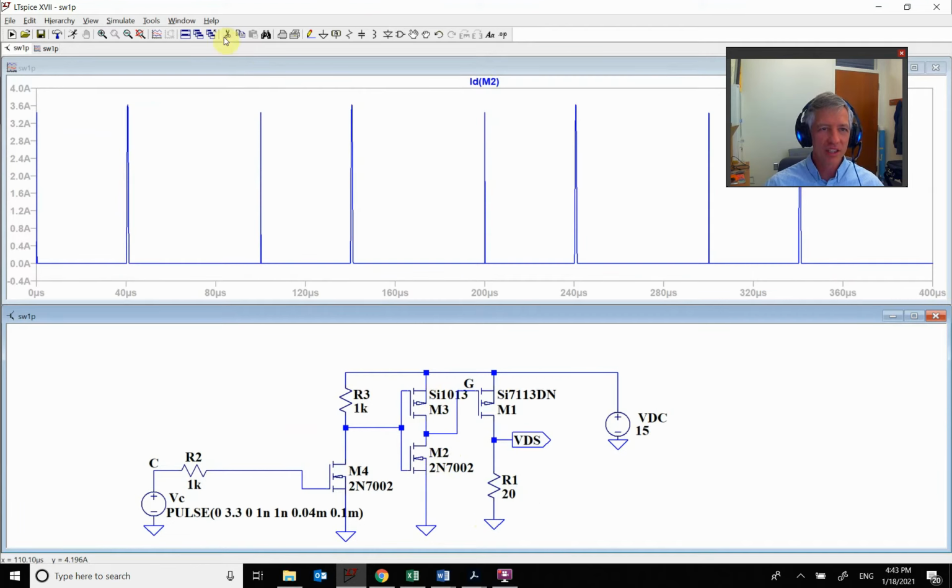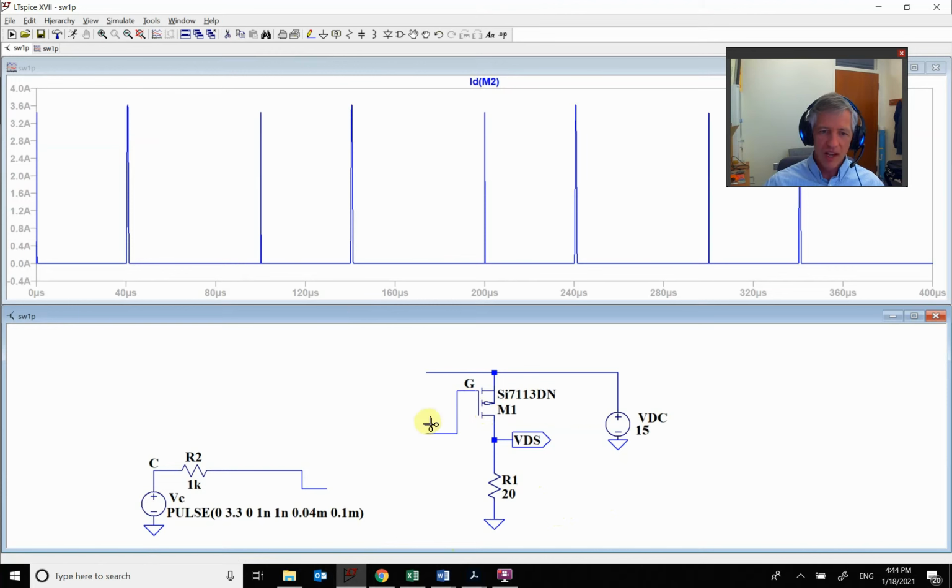So what we can do is we're going to have one of these level shifters to this one and one of these level shifters to the other one, and then I'm getting more and more transistors to get all this to work, okay? So there's other ways to do it. This stuff that we're doing here is all called a gate driver. So we're basically creating circuitry to drive the gate of the transistor, okay? So they actually just make little gate driver circuits that we can play around with.